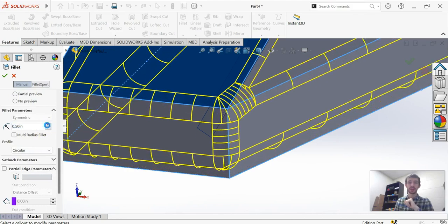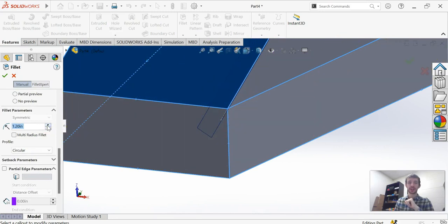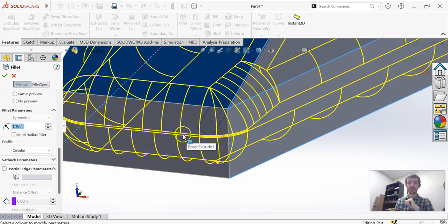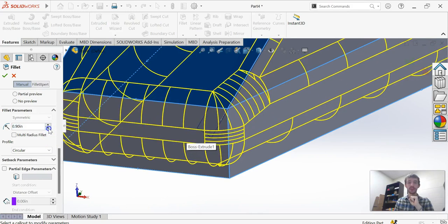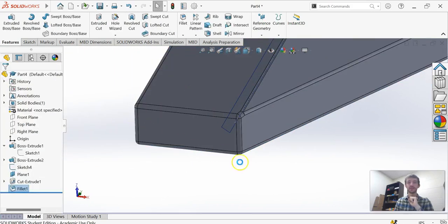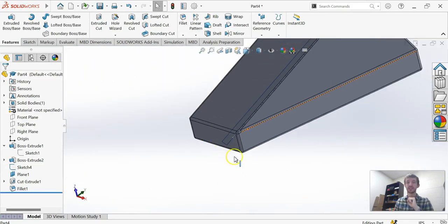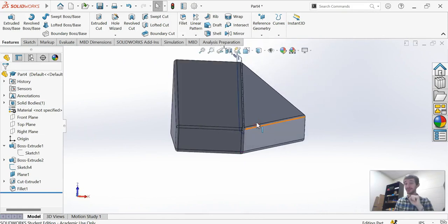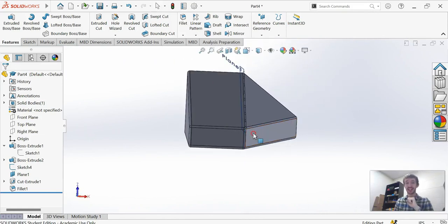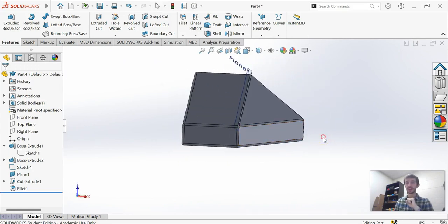I can change the size of that fillet. Make it bigger. The one thing it won't let you do is get rid of a feature, so if you make it too big, it'll get angry at you and stop you. So, right there, too big. This is fine. You can still see that flat face a little bit. If I go any bigger than that, that flat face disappears and it can't let you do that with a fillet. Okay, making it go down to a more reasonable size fillet. That looks nice. Now with that, I have just rounded all of my edges. Every single one. Boom. Nice, huh? Pretty cool. I like it. It's good by me. So every single one of those edges has been rounded, and it looks good.